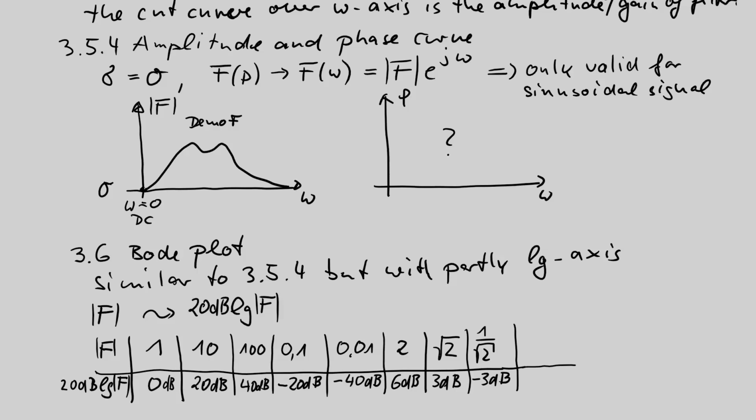Then a very important value is 0. If we have no gain, if there is a broken cable, what happens with my dB value? The dB value is the logarithmic factor of 0, which is negative infinity. So the broken cable is a value we cannot draw on a Bode plot curve. And finally, maybe you should know what is 1 dB.